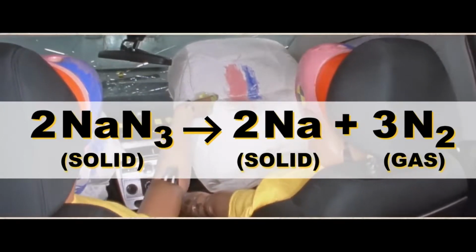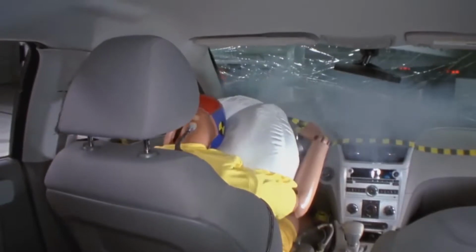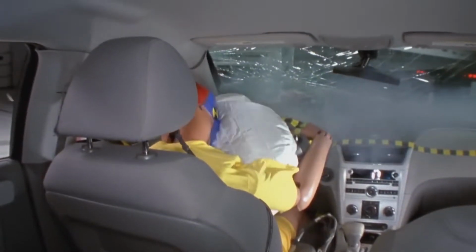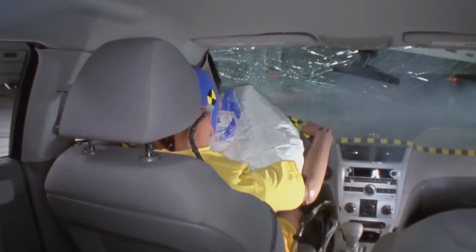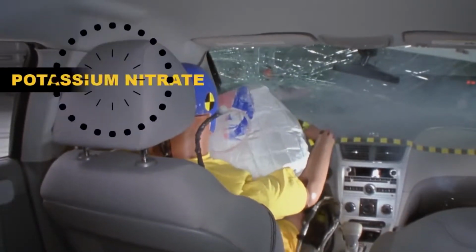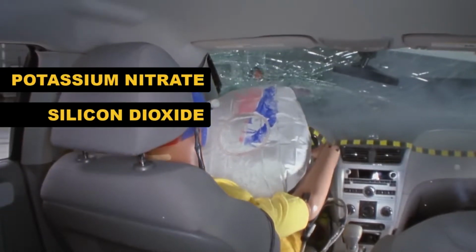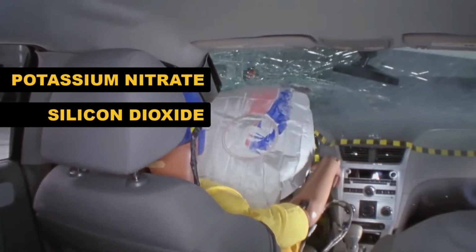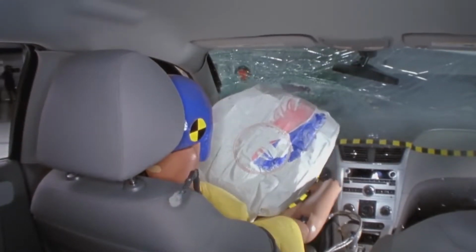Sodium azide can decompose at 300 degrees to produce sodium metal and nitrogen gas. The signal from the deceleration sensor ignites the gas generator mixture by an electrical impulse, creating the high temperature condition necessary for sodium azide to decompose. The nitrogen gas that is generated fills the airbag.